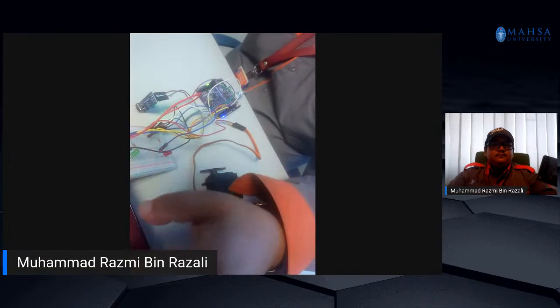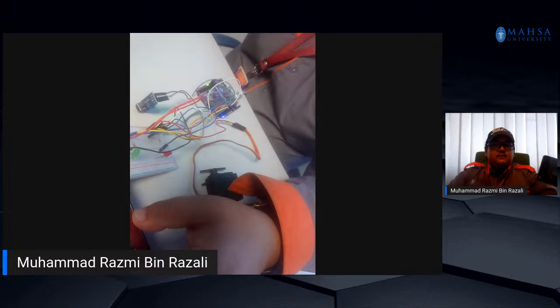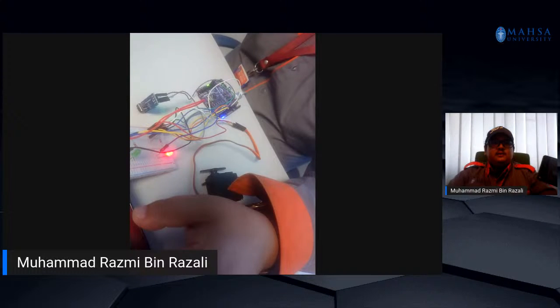Okay, so how does it work? We use the same command. In the board setup we use the pinMode command when we want to declare pin number 3 as output. Then in the void loop, we just add another line of code to represent pin number 3, because we already added the red LED to pin number 3.